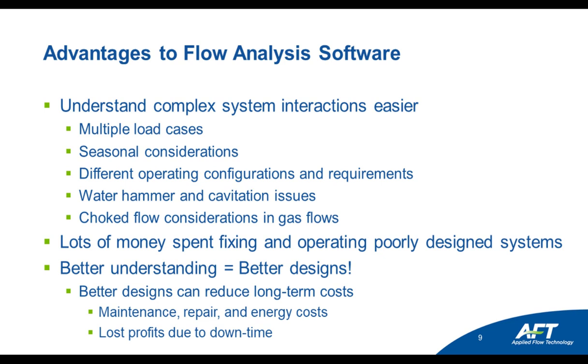If you're working with a gas piping system, which is outside the scope of this webinar because this webinar is focusing on liquids, you can have issues there too, where you might have choked flow, where decreasing downstream pressure is not going to give you any higher flow.